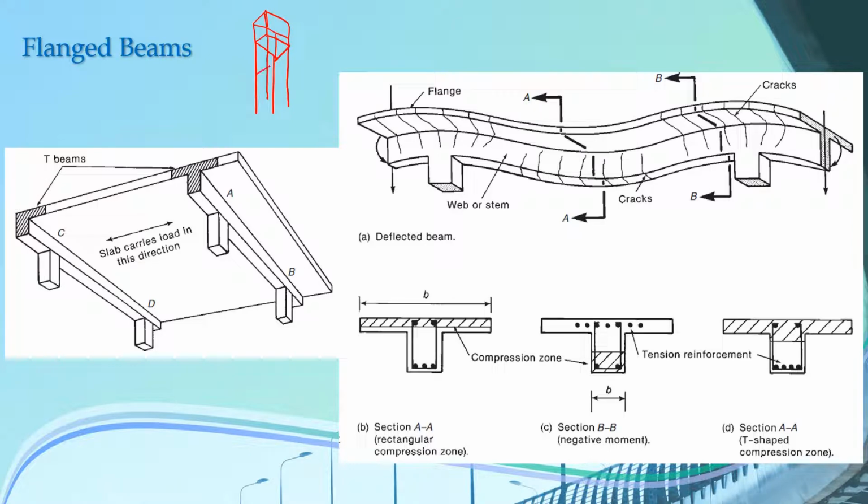And you can say that these RCC columns are supported by beams at different levels. So if you visualize this structure, then the beams that are constructed here are isolated beams. That means there are only beams here and there is no slab here. There is no monolithic construction of beam with any other frame element here.